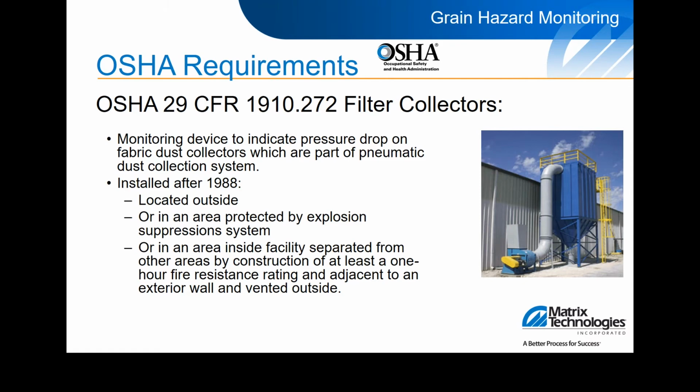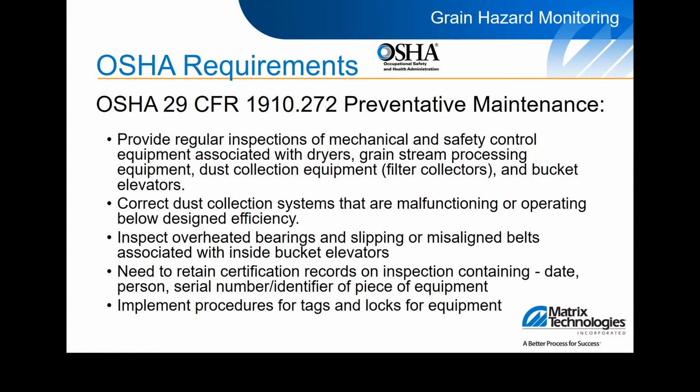Most sites will typically rely on both isolation and suppression for dust collectors, and it is important to document these within each facility. Under OSHA 1910.272, preventative maintenance is a key part of maintaining a facility. Many issues are caused by lack of maintenance of proper instruments or equipment, which is typically the main root cause of issues which can cause fires and/or explosions. Devices that are found to be not functioning properly at the facility need to be replaced immediately. Keeping spare and store stocks replenished for emergency service is also a good recommendation for operations.